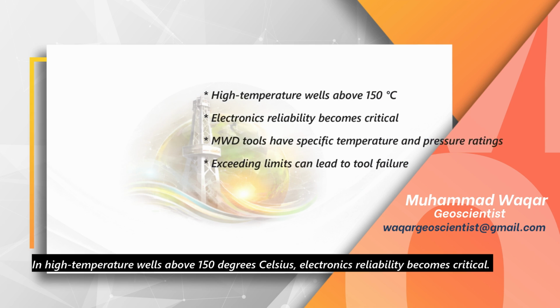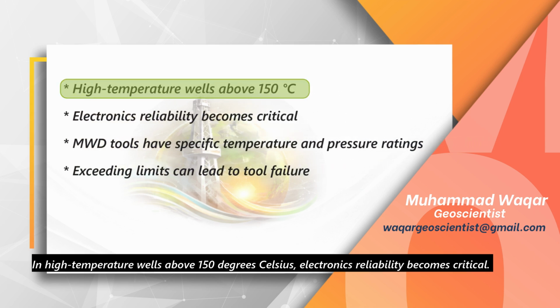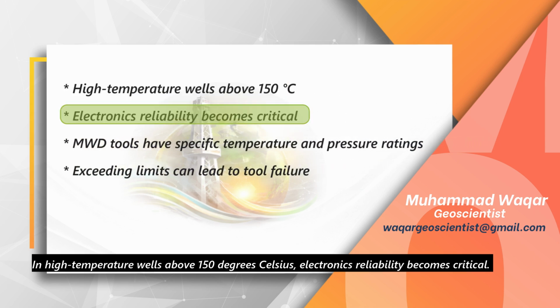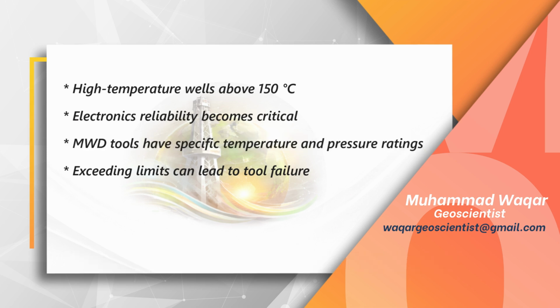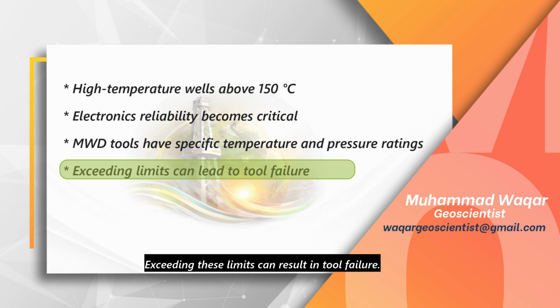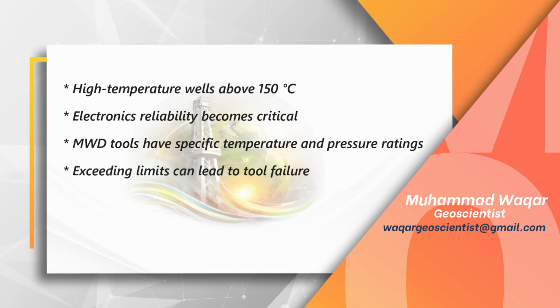In high-temperature wells above 150 degrees Celsius, electronic reliability becomes critical. That is why MWD tools are rated for specific temperature and pressure limits. Exceeding these limits can result in tool failure.